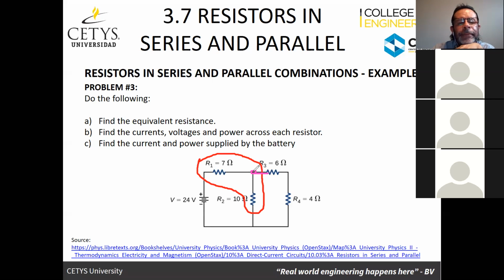Yes, sorry, yes. Now, well, we could say they're in parallel. Well, no, because for them to be in parallel, here they're joined in one terminal, but over here, the other terminal is connected to something else. For them to be in parallel, these two terminals would have to be connected together, and they're not. So this isn't a series or parallel connection either. We can't start off there.